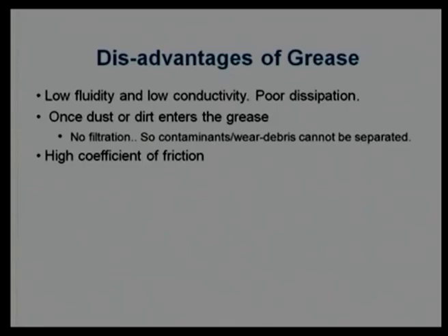We mentioned the advantages that grease avoids contamination coming into contact with the solid surface. It prevents the contamination from coming into contact, but the problem is that once the contamination starts coming, one way or another, and reaches the surface, then grease will try to retain that contamination on the surface.